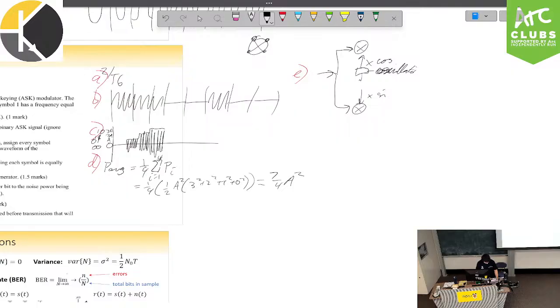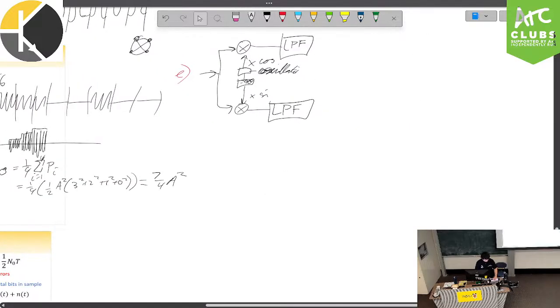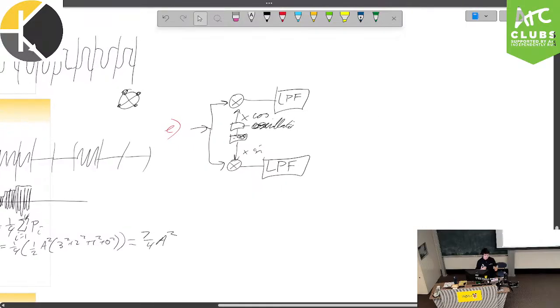and a 90-degree phase shift for that. So that gets us most of the way. As we saw in our diagram previously, we like to chuck in a low-pass filter, just so that we do not get a super high frequency out of them. We would just want to get what's low with them. And that gives us pretty much just the amplitudes of the sines and cosines that make up our quadrature.